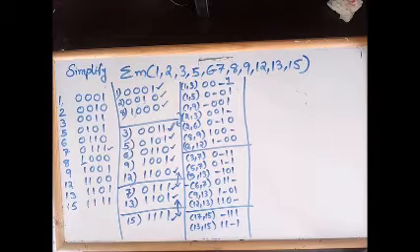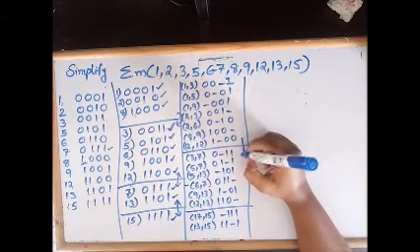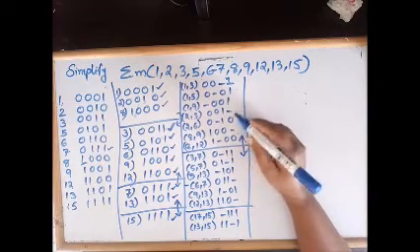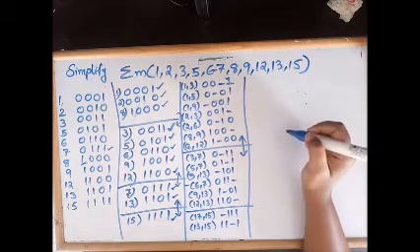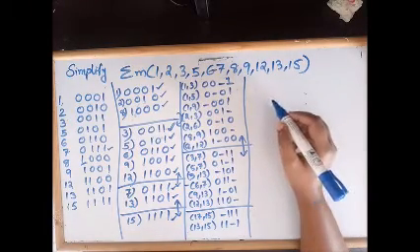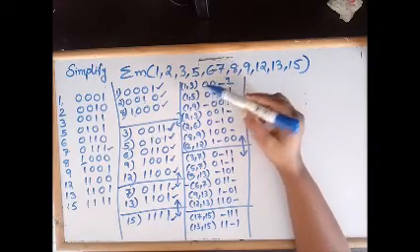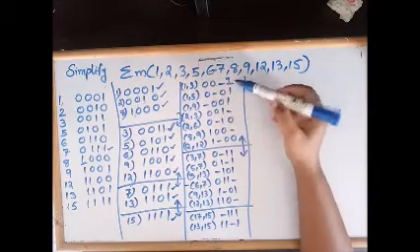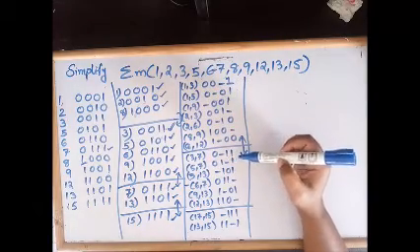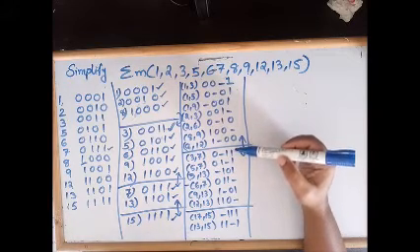So in the next step we can follow the same procedure. Again we will compare the adjacent groups and combine the terms with a single bit change. So again perform the same procedure. When you combine this, the first element is 1,3, and we can check with 3,7 and identify the number of bit differences.